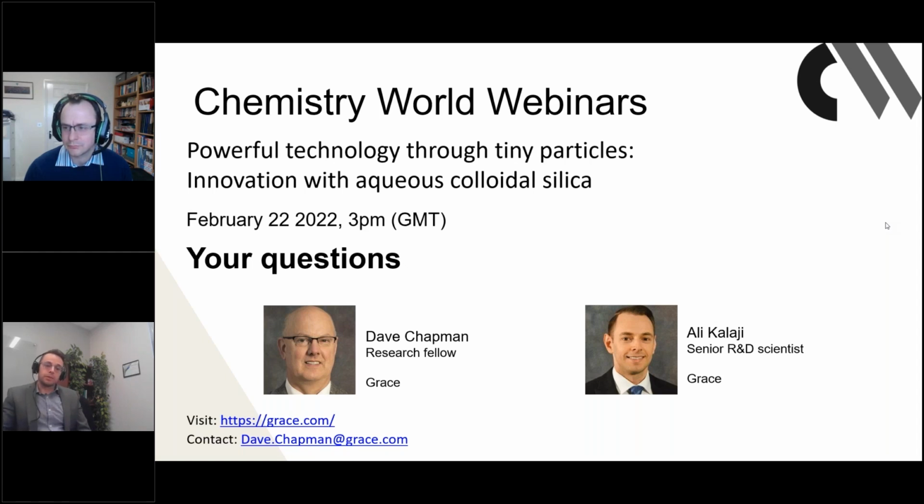But we're also able to, as Dave mentioned, make distributions of polydisperse or polymodal grades by causing multiple nucleation events and actually forming a wide distribution. And then we can also broaden the modes themselves. So we have different ways, by tuning the reactor properties and the reactor conditions, to give us different particle size distributions.